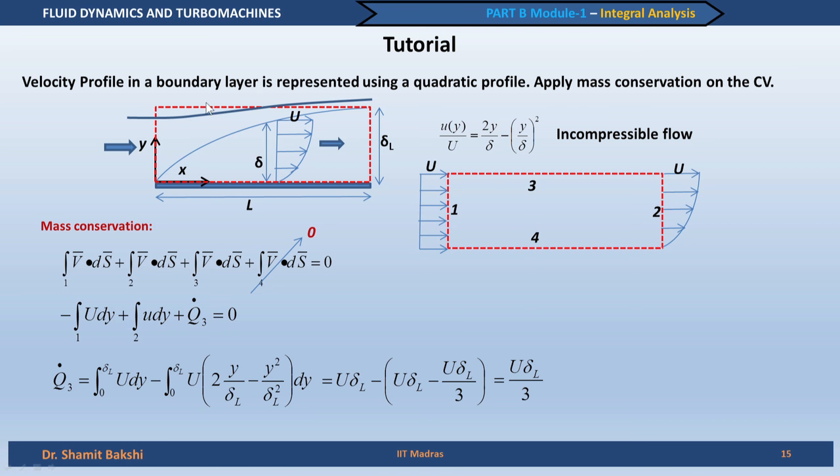exiting the control volume taken within the boundary layer and a little portion outside the boundary layer. So, this bending of the streamline is nicely demonstrated through this problem. But if you go further above, then the streamlines will be straight because they will represent the uniform flow in the free stream. Very near to the boundary layer, there will be a bending of the streamline, although the entire region is basically inviscid. So, this is the first problem.